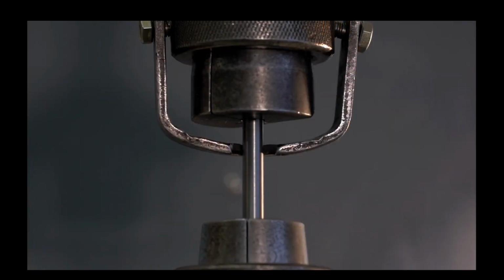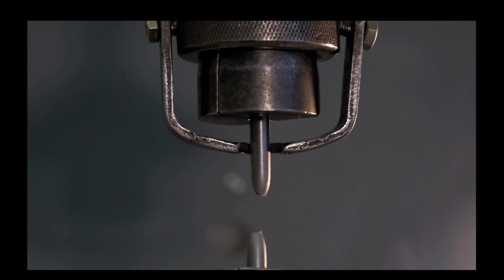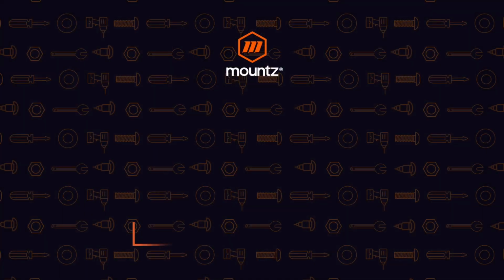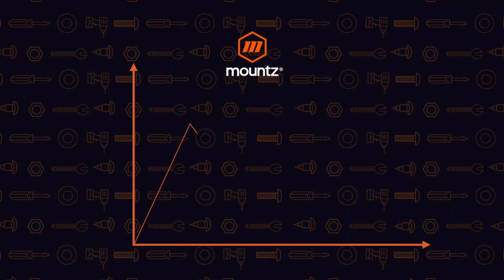Here's an example of a rod that's being pulled. You can see at a certain point, the rod will begin to deform and then eventually break. In this case, we have reached its tensile strength when it has completely failed. But there is a point at which that fastener will no longer come back to its original size, and that is called the yield point.